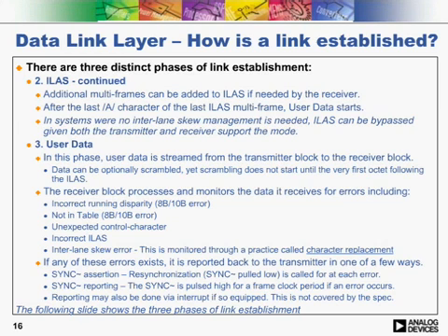ways. Sync bar can be asserted, which would cause resynchronization by sync bar being pulled low. Sync bar reporting: the sync bar could be pulsed for a frame clock period if an error occurs, and reporting may also be done via interrupt if so equipped, but interrupt is not covered by the 204 specification.